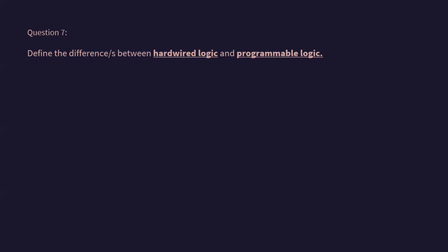If one of them becomes logic 0, maybe if you step off the foot pedal, then you have logic 0 on one of the inputs, and you do not have both logic 1s, then the blade stops. So this would be a hardwired logic because there is no software needed for that.